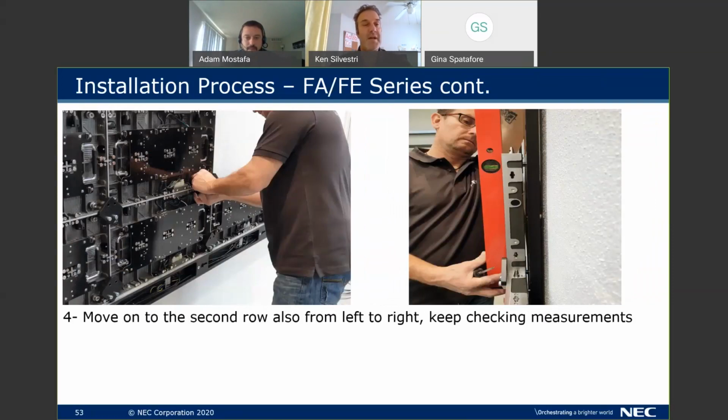Continuing, you start with the second row of modules. You will see on the left side a square, or let's say a diamond block, connecting the 4 modules together. 2 of the 4 screws are in there. When the technician is finished with that whole first row, you go back and put 4 screws in that, and you tighten that block down considerably. That is going to bring those modules into a Z-axis alignment. Then you can go back, and you remember on the previous slide, those little thumb screws that the technician was tightening.